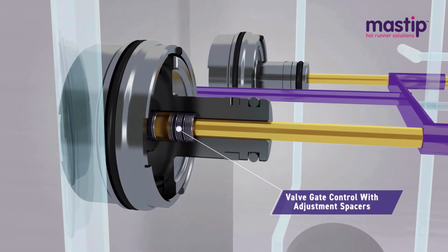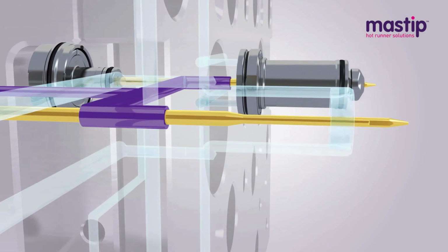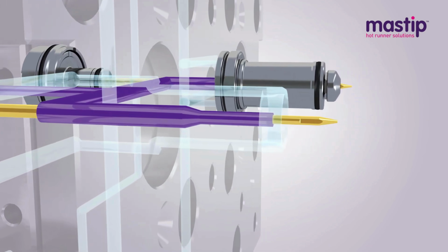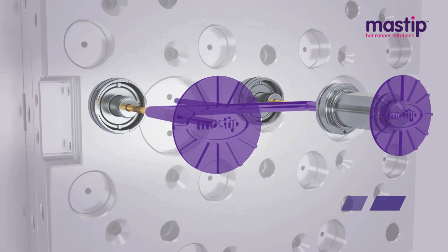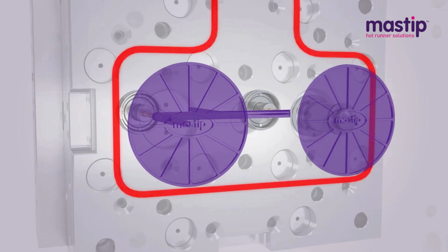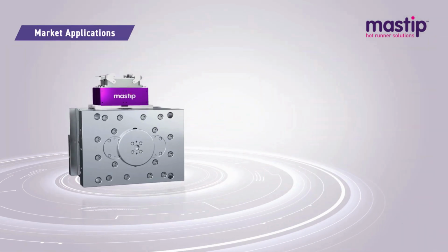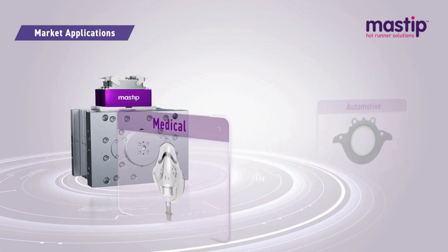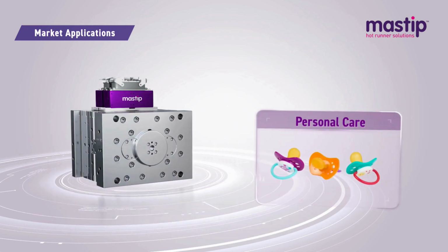Platinum-catalyzed cross-linking occurs within seconds at mold temperatures between 140 to 200 degrees Celsius, enabling high-volume automated production. LSR injection molding produces medical implants, baby bottle nipples, respiratory masks, electronic seals, automotive gaskets, wearable devices, and food-grade components with exceptional consistency and minimal flash.